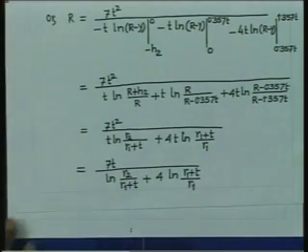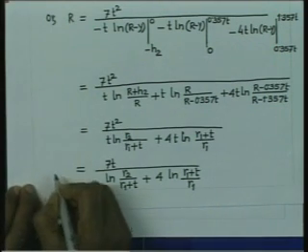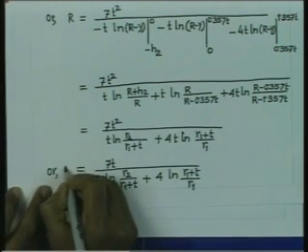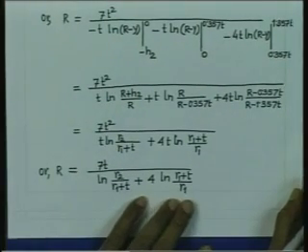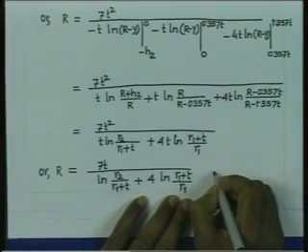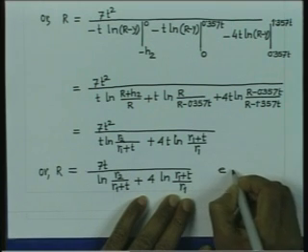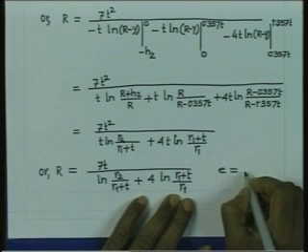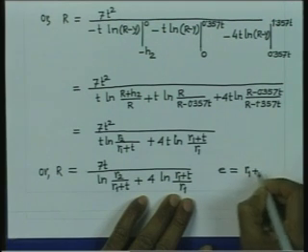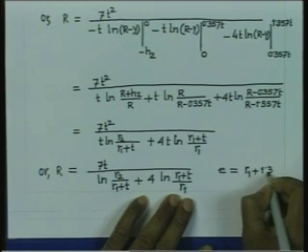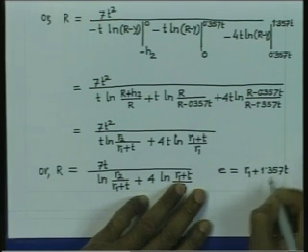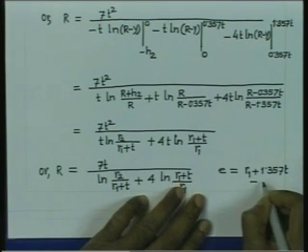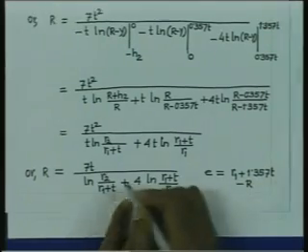So, that is the value of the radius of curvature of the cross section, and since we are interested in calculating the value of eccentricity, eccentricity is going to be given by R bar, which is nothing but r1 plus 1.357 t, minus R, and R is already here.